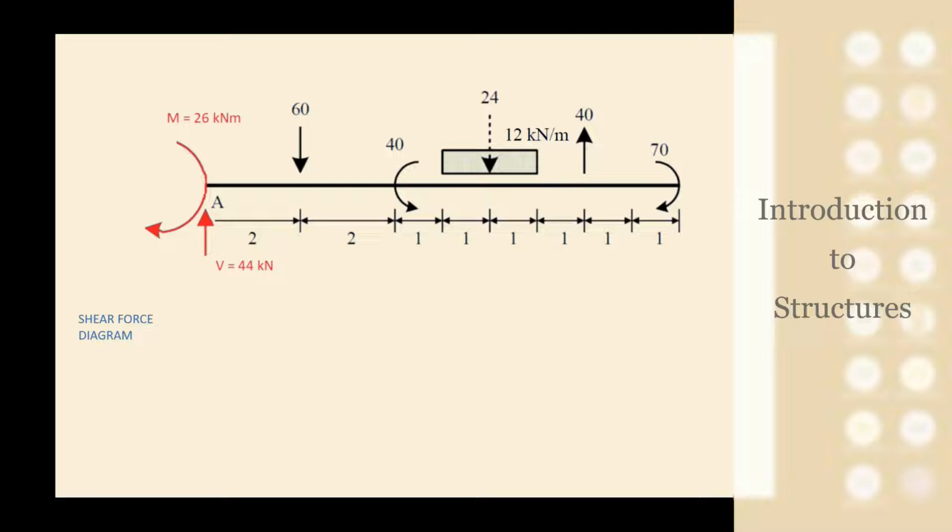So in order to sketch the shear force diagram, because we have learned a few things already about the shear force diagram, what we need to anticipate are the sudden changes we are going to see in this diagram. So in the first place, we need to sketch this horizontal line that represents the neutral axis. You will understand why it's called neutral axis in the second semester. But it's a horizontal line for now that represents the beam and is the reference for our diagrams, because in the diagram we're going to sketch the values of the shear force at every cross section of this cantilever beam.